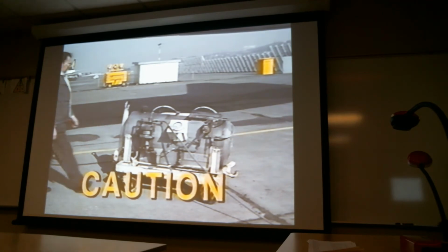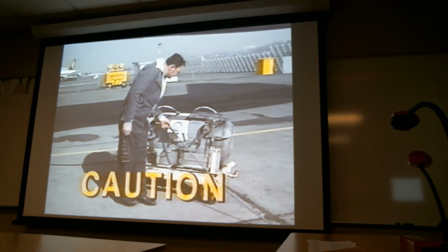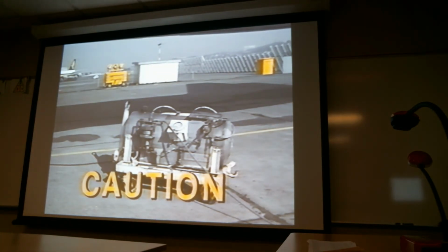Caution: do not exceed 150 psi fill pressure when servicing the hydraulic reservoir. Excessive pressure could damage the reservoir.